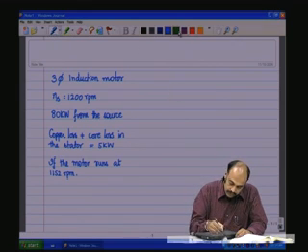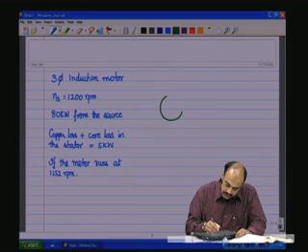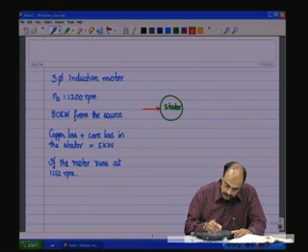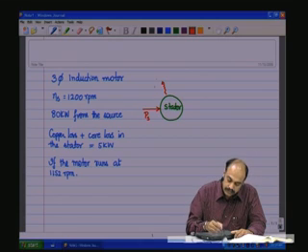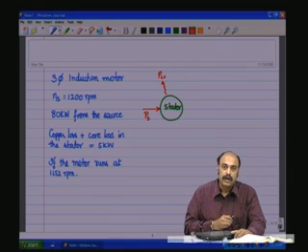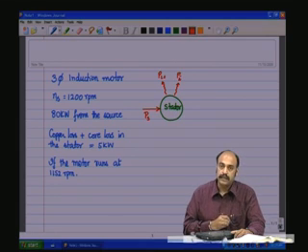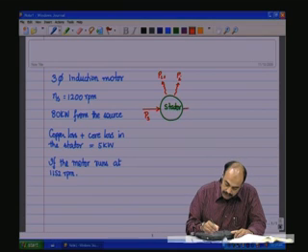So we have the stator, and to the stator there is an input power PS, and there is some loss, PLS, the I square R loss. There is also some loss, this is the iron loss PI in the stator, and the remaining power goes to the rotor, which is PR.